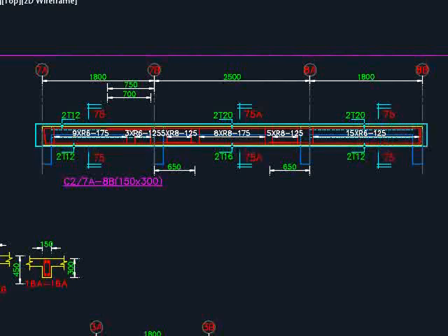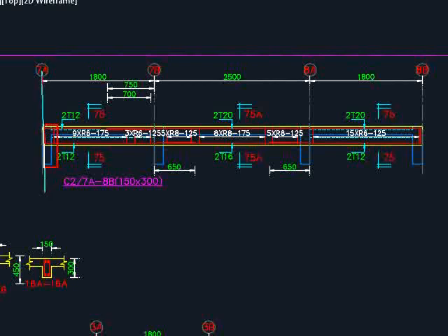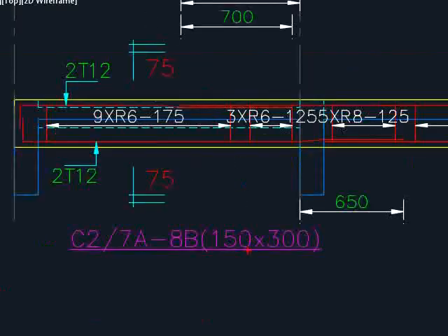This is the beam that you are talking about, and there are incoming beams. And you need to be careful, this incoming beam needs to also be in line with your structural key plan in terms of its positions, whether it is on the edge, or whether it is at the center, or whether it is at the offset distance. And then you need to indicate the reinforcement bar. Don't forget the naming needs to indicate the size of the member, which in this case is 150 times 300.